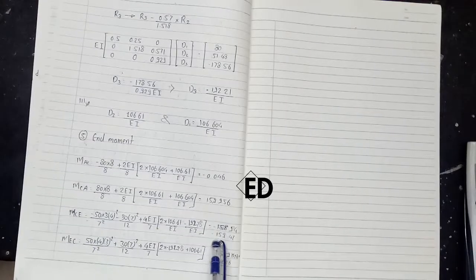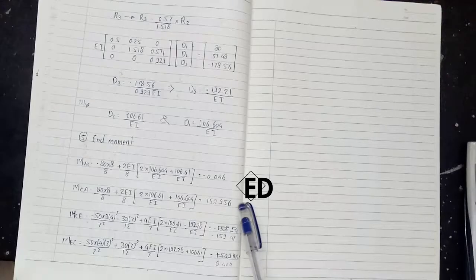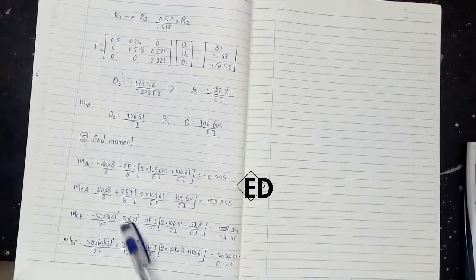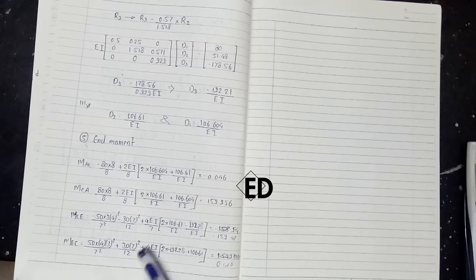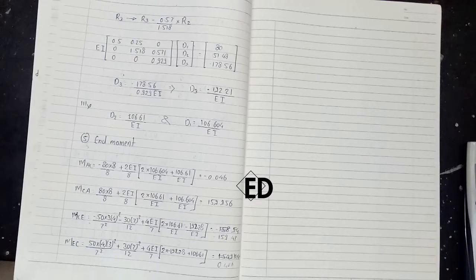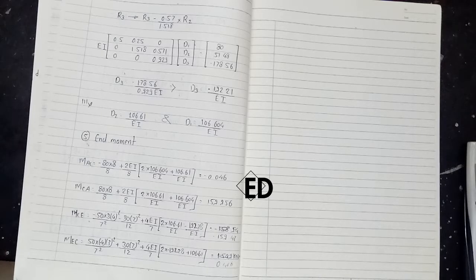So we get minus 159.47. These two will be similar. And the moment at E to C is P A B square by L square plus W L square by 12 plus 4EI by L twice theta E plus theta C. So we get 0.486 kN. Thank you.